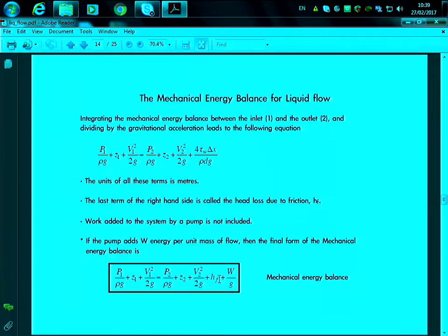In general, in most engineering aspects, when we're referring to pipelines, they always tell you in meters, okay? So we normally look at head losses, head pressure, head, and always when we say head, it's always meters. So we divide everything by gravity, and by dividing by gravity, we basically convert everything to meters. It's a more gentle unit, and then everybody understands them. But it's the same thing, okay?